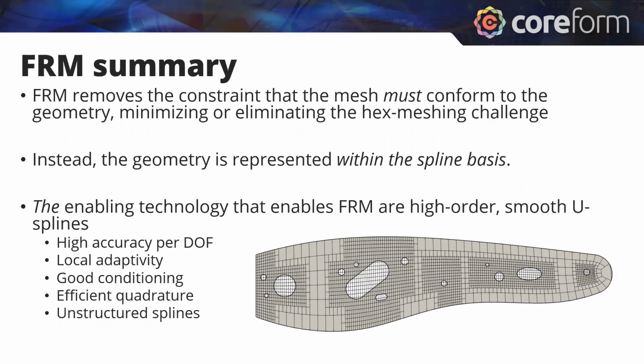T-splines also allow local refinement of geometry. How does U-spline technology differ from T-splines in terms of local refinement? Yeah. So Matt, you may be one of the experts on T-splines on the call today, but T-splines were developed for design purposes, specifically to try to build smoother surfaces for, say, automotive body styling.